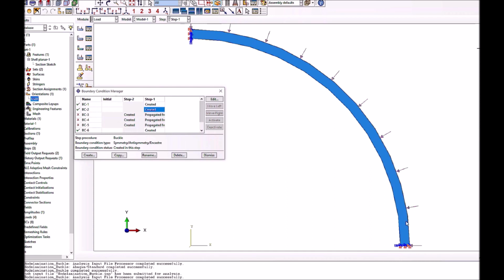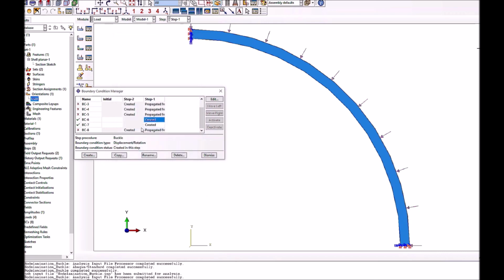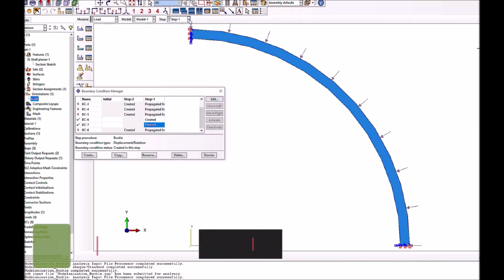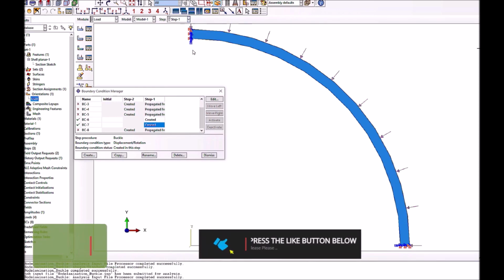In addition, since this can move in reality, but it's also constrained with the other part, to avoid that motion and to create some kind of constraint, I am using an artificial constraint. So that's what I've done here. I have fixed this point in the u1 direction and this point as u2 direction to provide some resistance. Otherwise, you will have free motion here in this direction, and here in the y direction. So your collapse pressure or implosion pressure will be really low.